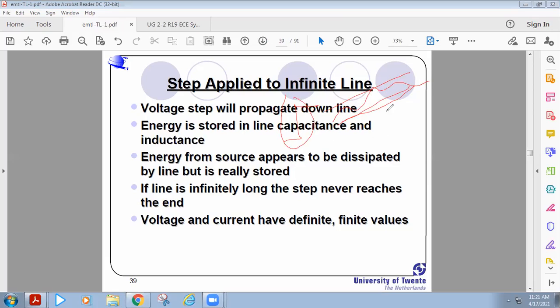At the same time, we consider that this transmission line is neither a lossless line nor a distortionless line. It means it is considered a general lossy infinite line. That's why the transmission line itself contains primary and secondary constants, or RLGC parameters. What exactly does it mean? It contains some resistance, conductance, capacitance, and inductance.